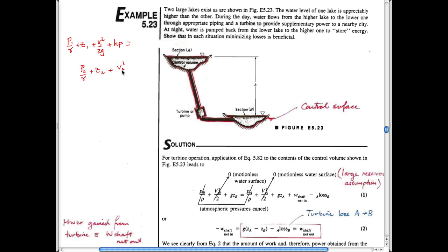Plus the velocity term. Plus the losses in the system. And so it's actually an interesting example because it shows that it's quite important to write them upstream and downstream, and how you define upstream and downstream. So upstream and downstream basically has to be written relative to the flow directions. Perhaps not surprisingly, but I guess this kind of illustrates it. So this is the flow direction, then by definition this is upstream, and this is downstream. I'm sure you're not surprised by that, but sometimes it's worth reminding ourselves that that's the case, because sometimes it's not quite obvious.